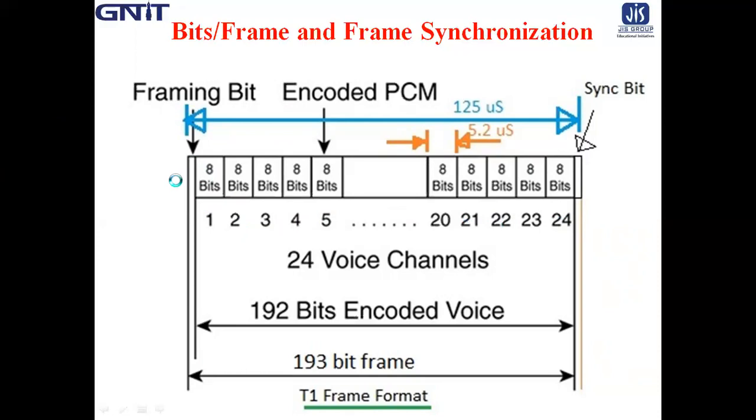Those are both in binary form. So one can easily say that the frame synchronizing bit is also an information bit. So how is it identified as a frame synchronizing bit? There may be a chance that the receiver takes it as an information bit.